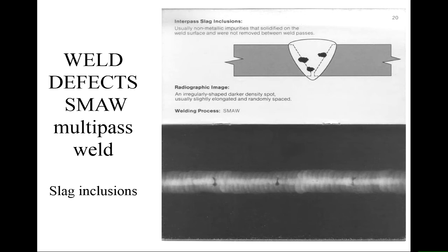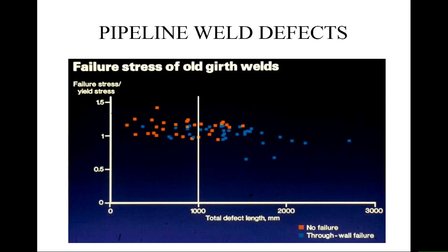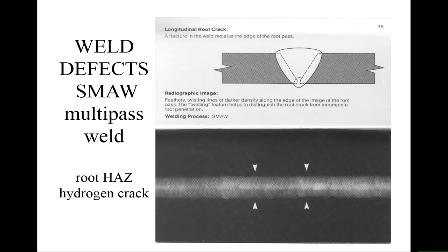It is with the density of the materials that are sampled by the X-ray. Tungsten is a heavy metal, so it has a higher density. Higher density means they will appear whiter in the radiograph. It is the same principle with the X-rays in health applications. Our bones on any X-ray will appear how? Whiter or darker? Whiter, because of the higher densities, and the organs will appear dark. So that's tungsten inclusion.